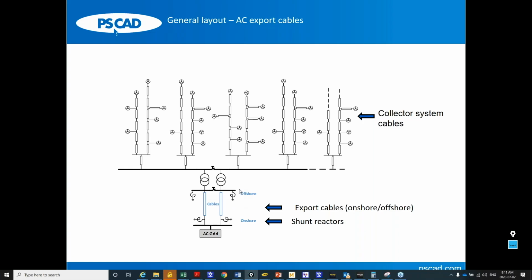So you need to have reactors to compensate for the capacitive reactive power, but probably just fixed shunts are not sufficient. In most cases, fixed shunts are not sufficient. You need to have some form of dynamic reactive power compensation, STATCOMs or SVCs. So they will all be connected, mostly to the offshore substation. So all these must come into the picture.